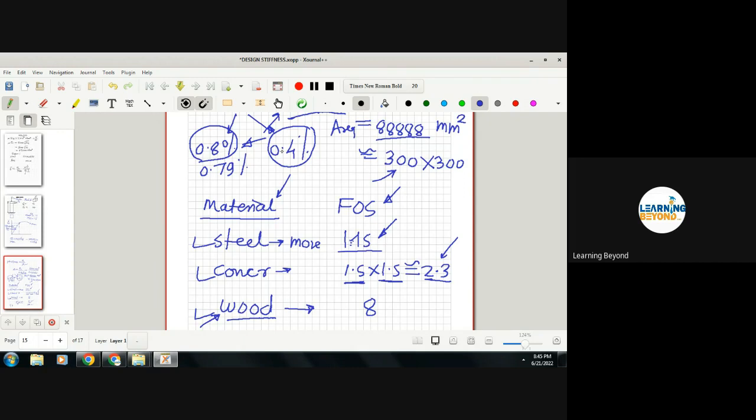So you can see this 0.8% we have given in our code, and UK is saying 0.4%. So what may be the reason? Definitely there is some reason. Otherwise, as an engineer or as a logical person, I'm saying we are over designing the structure. Like this 0.8%, I'm taking more steel in column unnecessarily because this is the minimum steel criteria, and here it is 0.4% in UK. So somebody may say that Indian people are designing heavy. It's not exactly the case. Don't come to the conclusion only by the logic of the numbers.